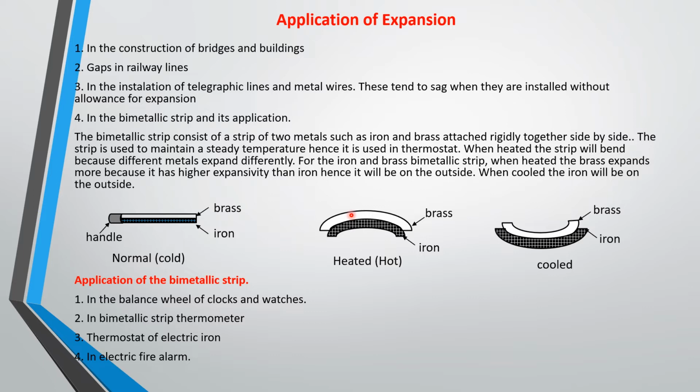When the bimetallic strip is cool, it will straighten up and make contact. That okay, it will make contact. Then as it is getting hot, it will start to bend away from the contact, and once it bends away totally, the equipment will trip off. Then when it cools back again, it will make contact, and then the equipment will pick up again and it will continue to work. So that is how the bimetallic strip works.